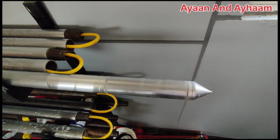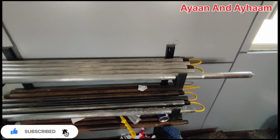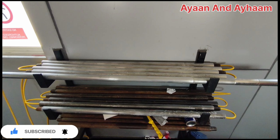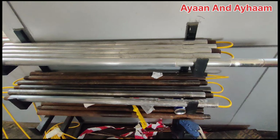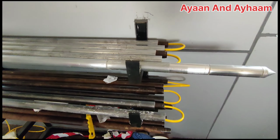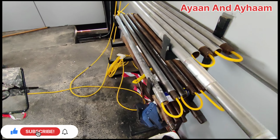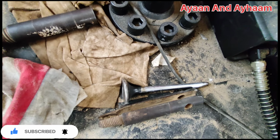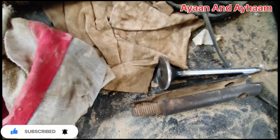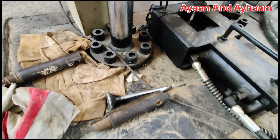This is the cone which we are driving, and this is the rod. Each rod length is 1 meter. The cone diameter is 5 centimeter, 50 mm. This is connected with the hydraulic pipe which is connected with the hydraulic jack machine, and this is the hook which we are using to fix or remove the rod. Each rod length is 1 meter.